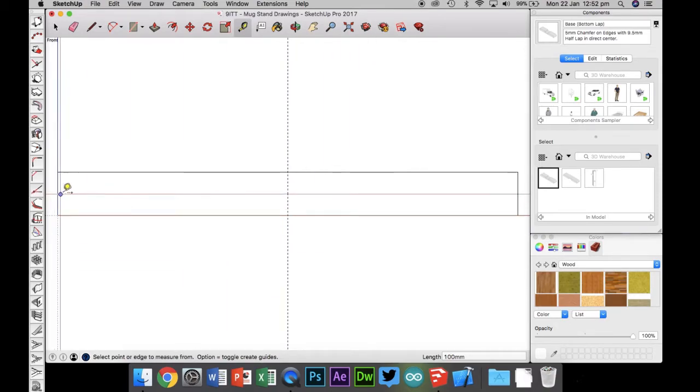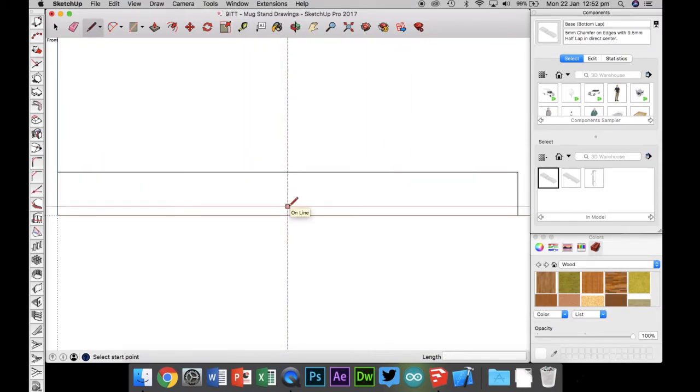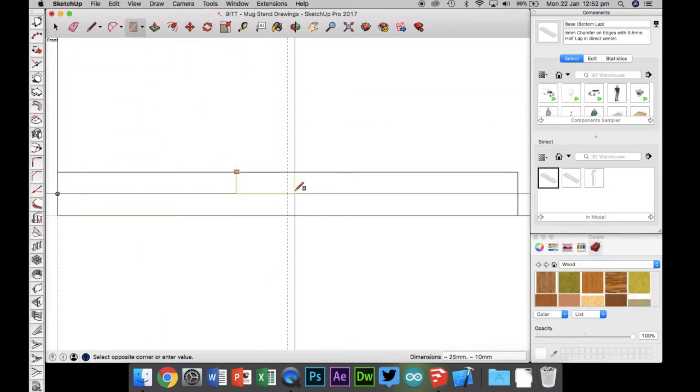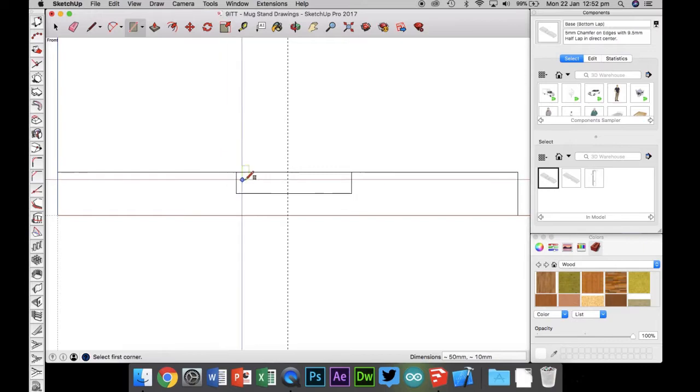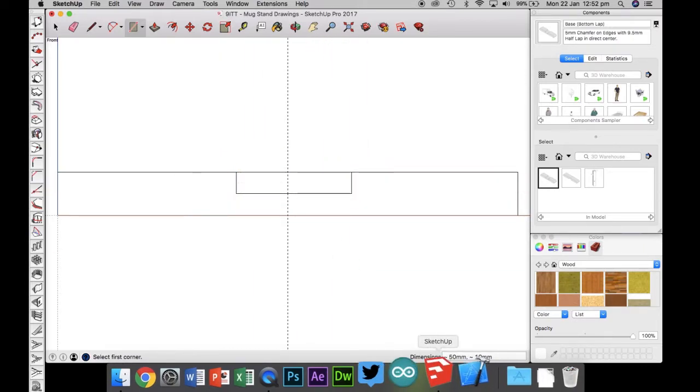When you measure from left to right and you locate the center, which is 100 millimeters, you now have this dotted line along the center, and that's really useful for us. We also know that with part C, we're going to be cutting out a rectangle around about there, along the top, directly in the center. But we can't just guess. We have to have it absolutely perfect or our parts aren't going to line up neatly.